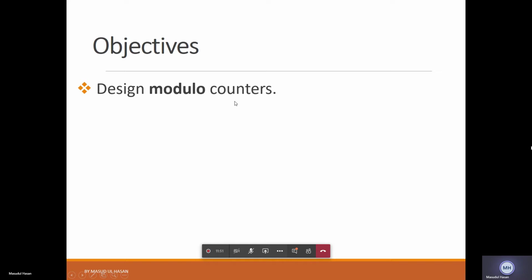Now here, this is a very important point to be noticed. We can play with the clock also. See here what we are doing, we are providing this clock to all of them together: the same clock to the first counter, the same clock to the second counter, the same clock to the third counter. If we are doing it like this, it means all the 3 are synchronized.